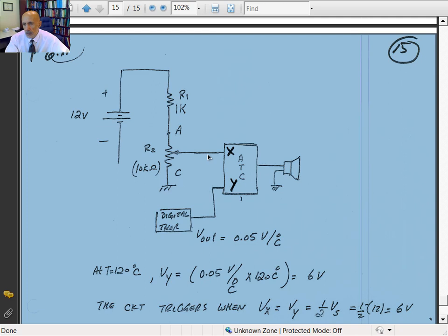It's called high input impedance. You can certainly use operational amplifiers for high input impedance. When you do that, you minimize the loading effect, so when you hook up the circuit, this voltage reference is not going to change, which is something you like to have.